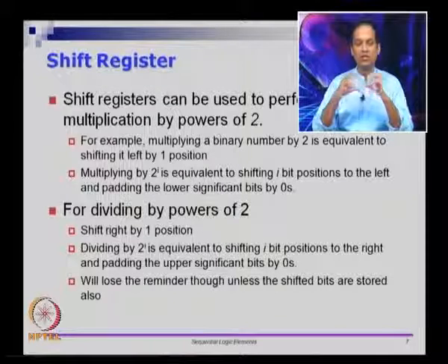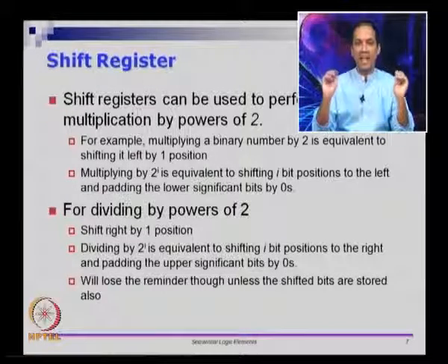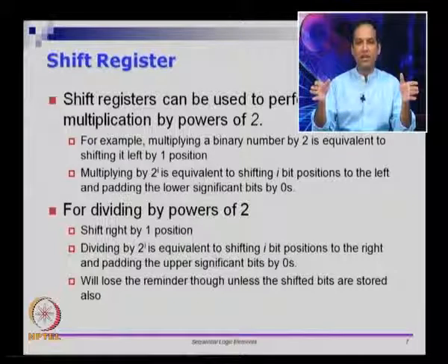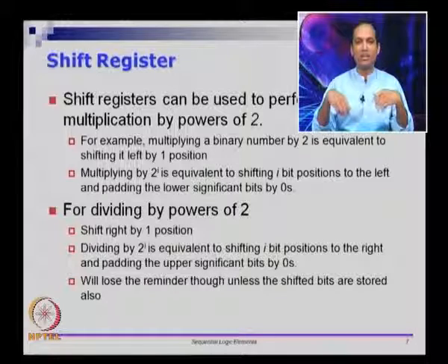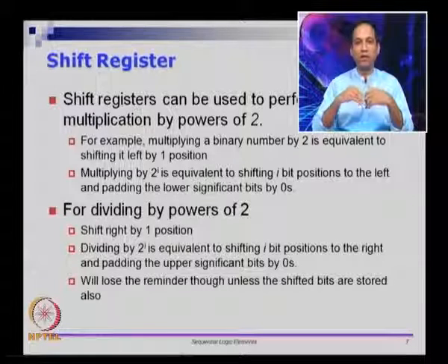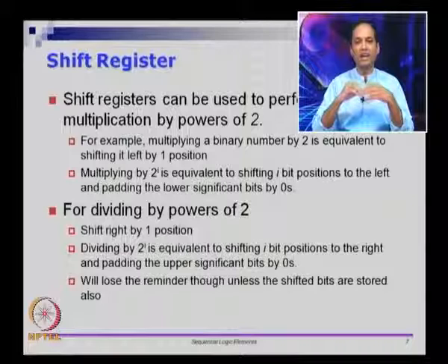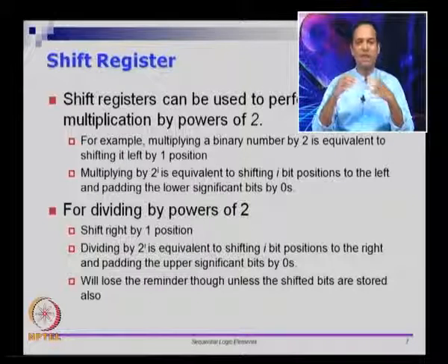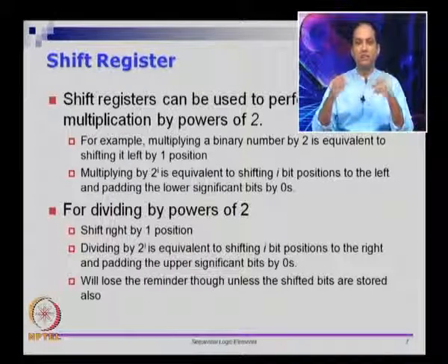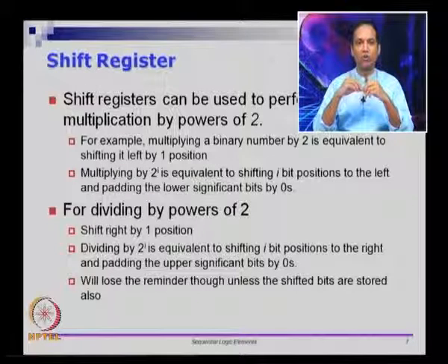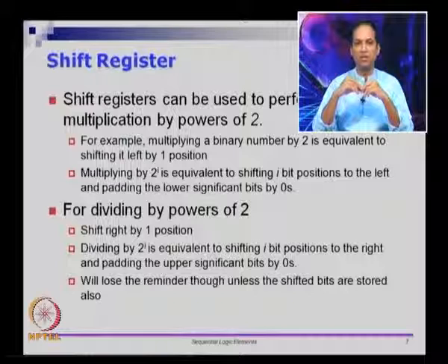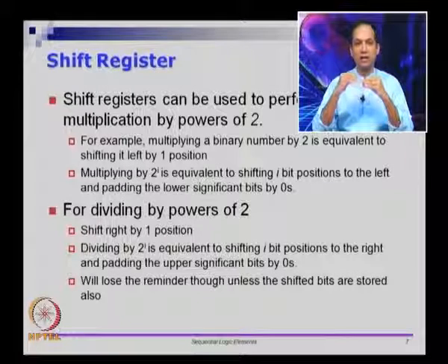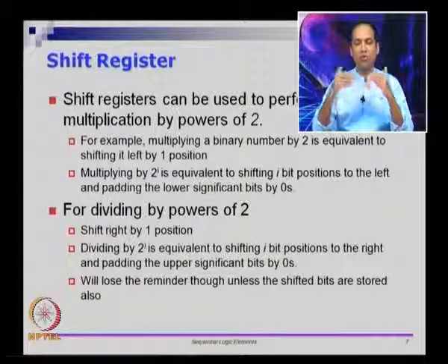So if I put some value n in a 5-bit register and right shift it 2 times, the equivalent value will be n divided by 4, or rather, you know the ceil and floor functions, it will give you the floor of n divided by 4, which means the integer that is lesser than n by 4 and the closest to it.